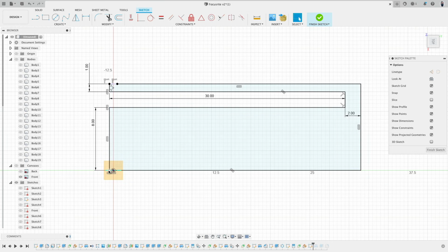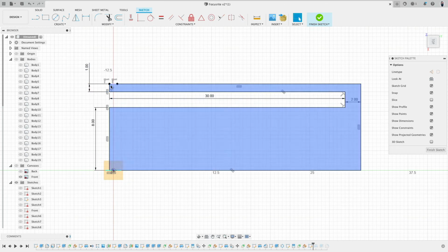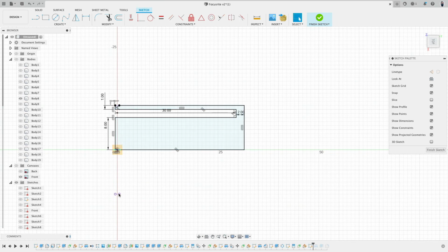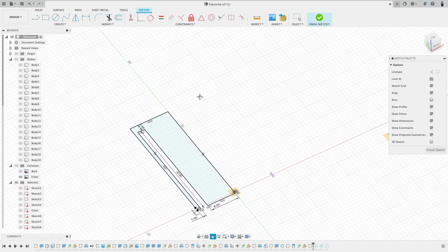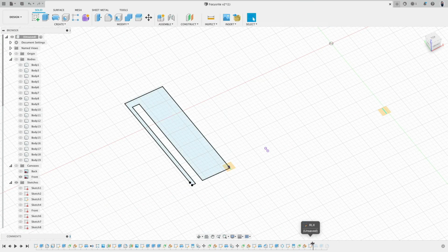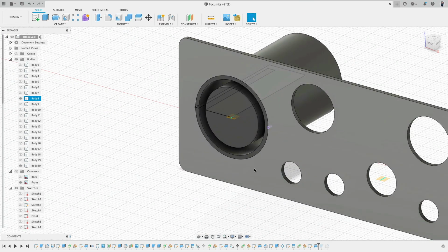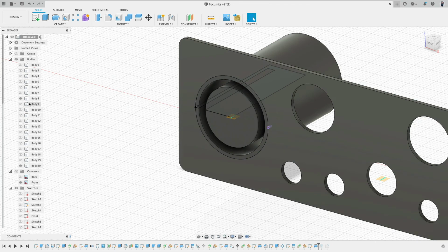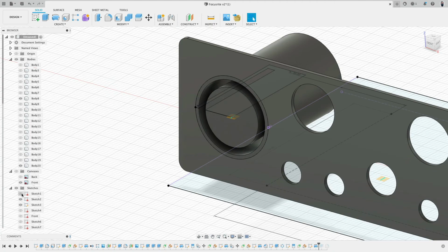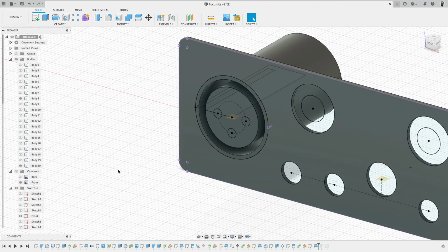Very basic. So 8 millimeter from the center, 2 millimeter here for the back. This inside is 31 millimeter from the ring. There's also the find intersection edge, because with this piece, I was able to do this rotation, very nice. And don't forget, we have actually this other sketch here. I call this front, so I find it easy.